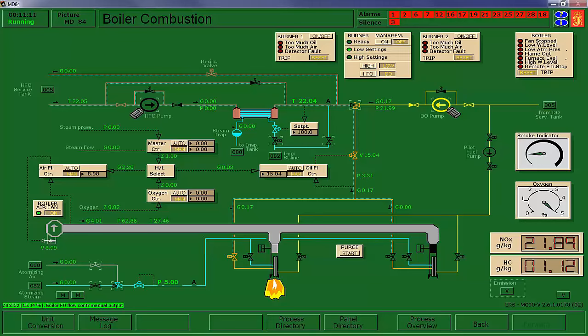So we're going to drop this down to a minimal, in other words, where this damper is basically closed, and do it in steps. I'll try 12, and let's try 6 here. I'm trying to keep this air-fuel rate from going up too much or down too much. And let's try 7 here, and let's go 3. So that damper is basically closed. It's going down as low as it can. And my air-fuel rate's coming down. This meter won't indicate till that gets below 5.